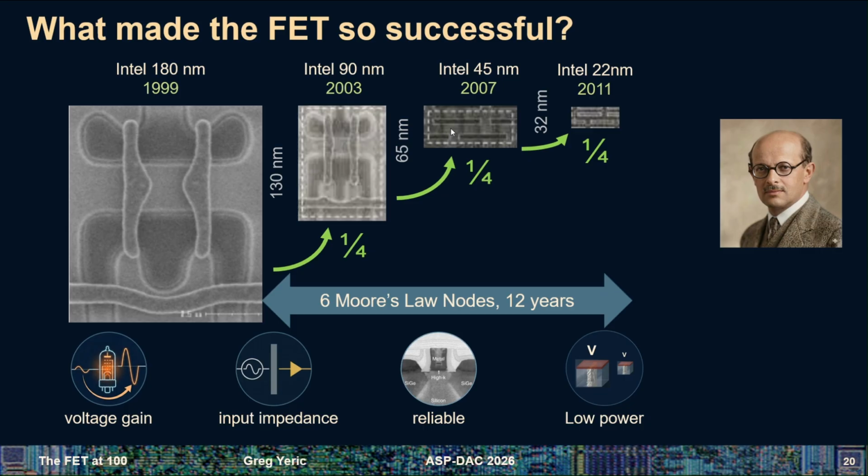They switched their form factor in modern processes where you really could only do straight lines with the limitations of modern lithography. So when you look back at this older node, you see we made the gate wider here because we want a little more room to stick a contact on there where we know there's going to be some misalignment over the process. So with a little more room there, and then the source and drain contact, bubble this out a little bit, make a little bit more room for the contact to land there. You don't get any of that in the modern era. So these bit cells that show the straight lines are less efficient area-wise than these, but we're enabling Moore's Law, so we came out ahead.